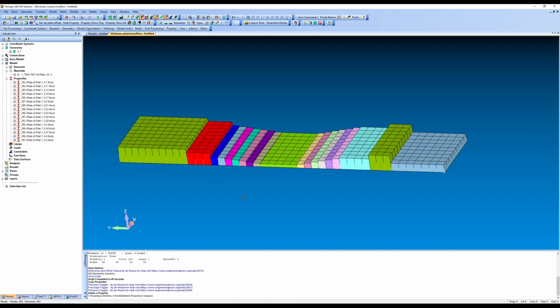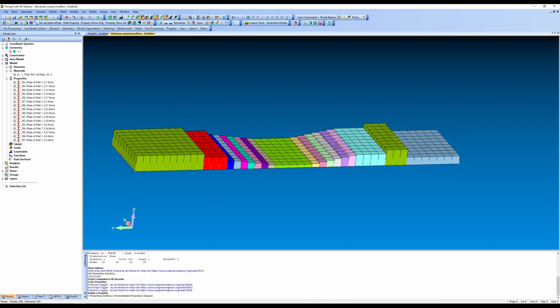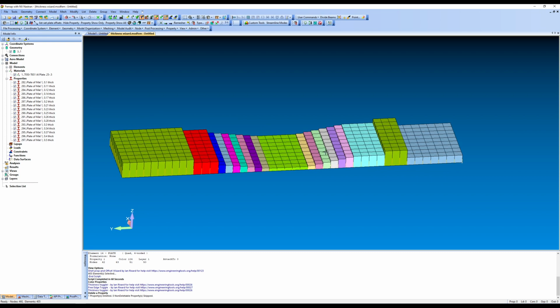If the script runs into elements it can't figure out a face pair for, it will make a group here and notify you that there was an error, and you can go set those manually. So depending on your geometry and your mesh configuration, that can happen sometimes.